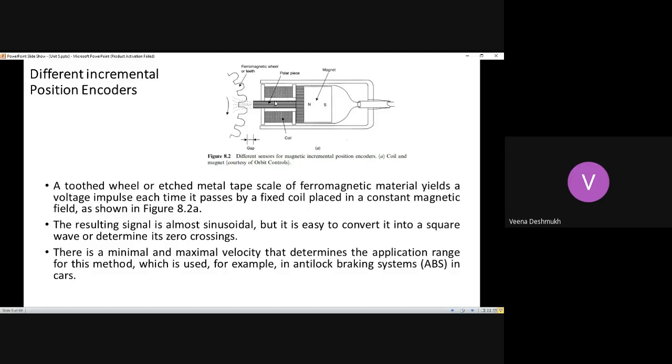By maintaining either a coil or a piece of magnet on which the coil is wound, with the magnetic field and the current flowing through them, you can get the position of the tooth, and the air gap can be counted. So basically this works on the magnetic induction principle. This is also like a positional incrementer, what we saw in the earlier case with the optical light.